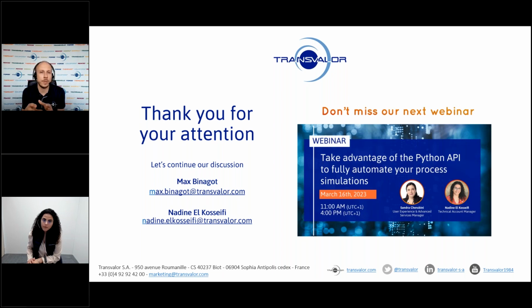If you have a template of formats, I think you can ask Forge for the list of all the nodes, their positions and the field values and the scalar results, and then export them to a format that you can use for another application.